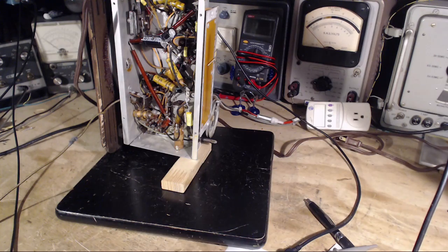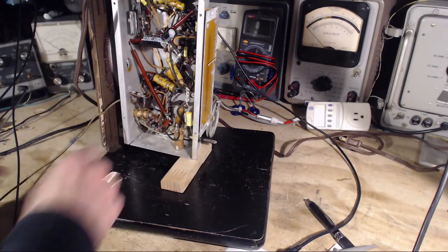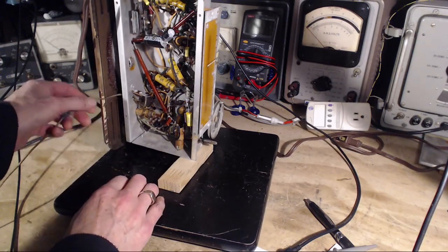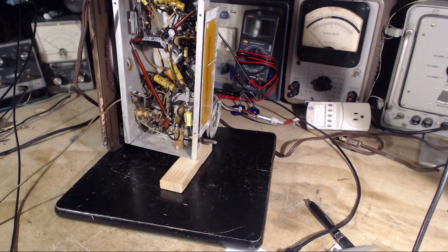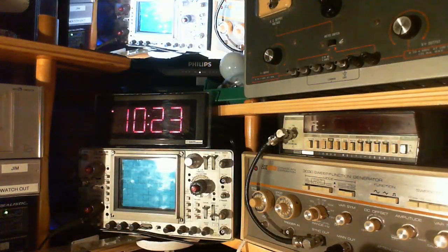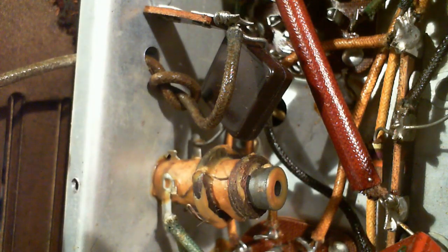Okay, let's take a look at the coil in question. It's this one right here, and you can see the antenna wire, and you can see where it comes right in here. So let's take a closer look at it. Okay, so let's just go over this. Here's the antenna wire coming in. Here's the capacitor the antenna signal is fed through, and you can see it makes a connection down here, one of the coil terminals.